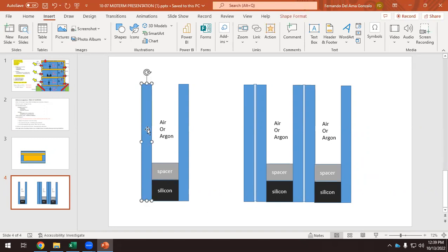And here we have the material itself, the float glass. So this is the float glass. Then we can have the laminated glass for security or for safety. We have this glue between two glass panes. And then we need the air gap. The air gap can be filled either with air or with argon. And we can have double or triple glazing.